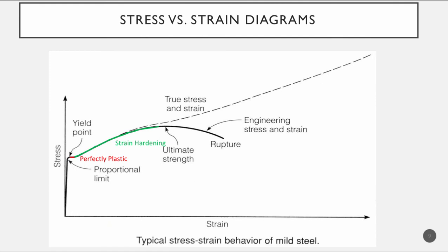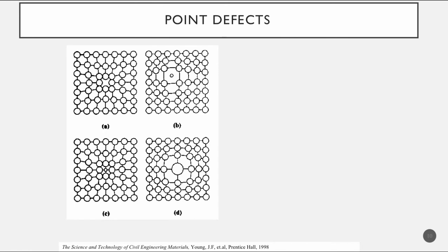So all of this cool shape on the stress strain diagram is literally from the shape and flaws in the lattice structure. So what are some of those defects? Well, there's really 2 that are the key ones. We have our point defects, and so the point defects can be A, an atom is missing. An atom didn't form, and so it changes the shape of our lattice. It causes some compression, and it's just hard for the line to keep slipping, or again, there's nothing to bond to because there's an actual hole, a missing atom, in the mix.